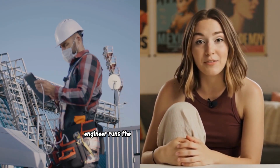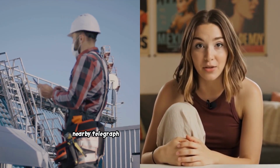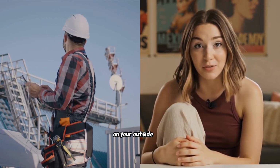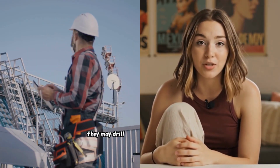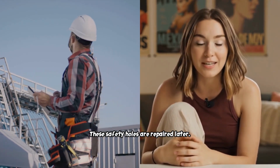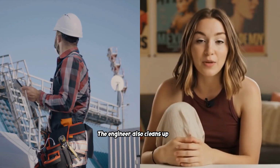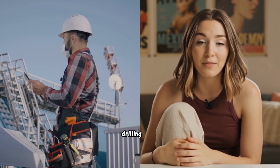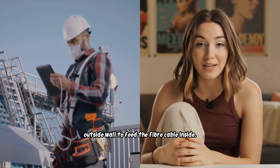The engineer runs the fiber optic cable from a nearby telegraph pole or an underground chamber. They connect it to a small junction box on your outside wall. At this stage, they may drill a few extra holes outside for ladder safety. These safety holes are repaired later. The engineer also cleans up well, so you will not notice them. The engineer carefully marks the agreed drilling point. They then drill a small hole through your outside wall to feed the fiber cable inside.